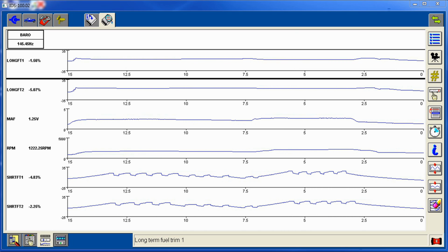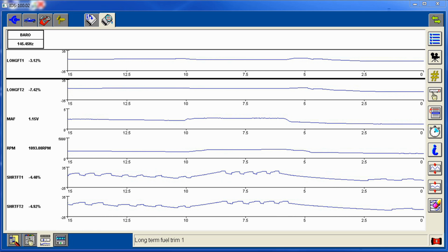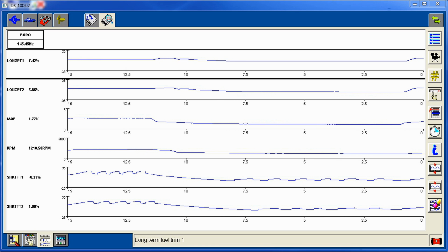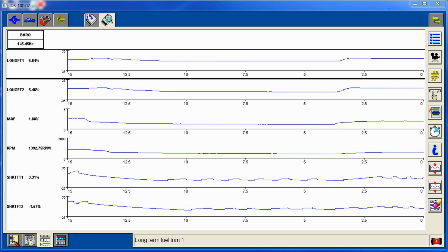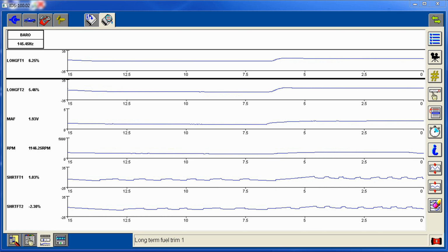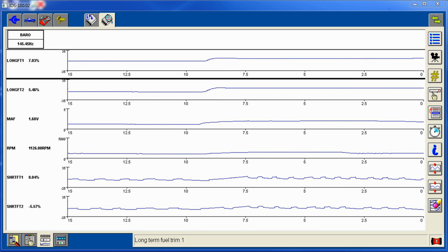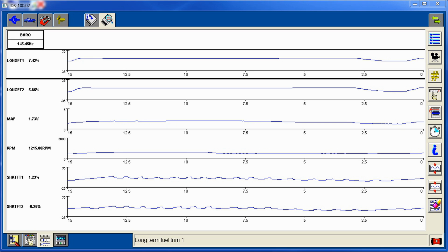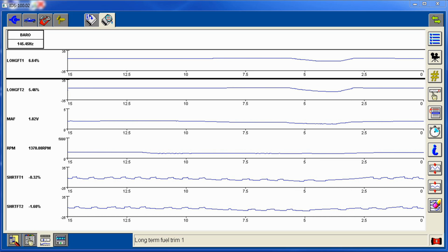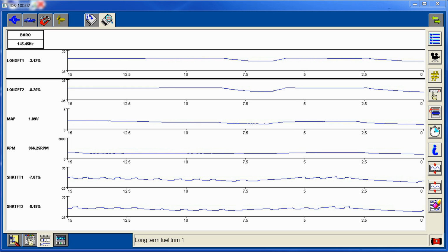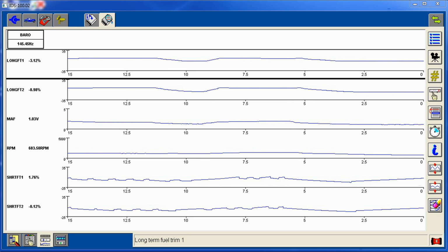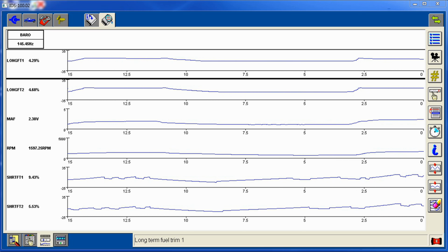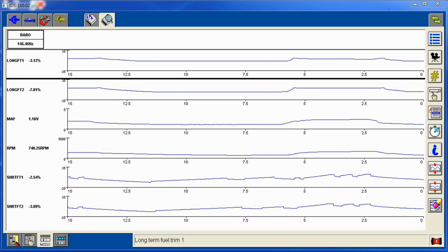And when you're at part throttle like that, 2,000 RPM higher, it's not a concern with engine vacuum leaks, because those show up at idle only. Anything above 2,000, 2,500 RPM is going to be a skewed sensor, okay, or dirty injectors not injecting enough, or your low fuel pressure to begin with. Any of those can cause the engine to go lean while driving. And in this case, it's the mass airflow sensor giving the wrong information. It's underestimating once you're driving.